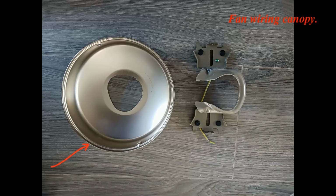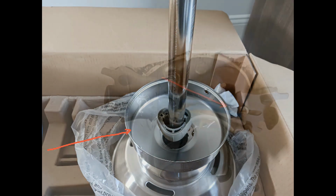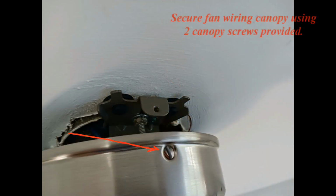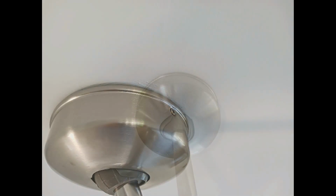Fan wiring canopy. Fan wiring canopy screws. Fan wiring canopy already inserted on the downrod in previous step. Slide fan wiring canopy upward the downrod and rotate canopy to match holes in the bracket with the holes in the canopy. Secure fan wiring canopy using 2 canopy screws provided. Tighten both screws.